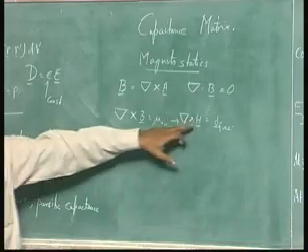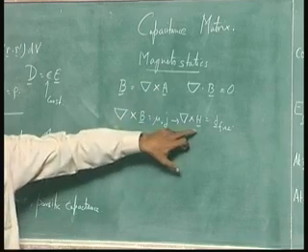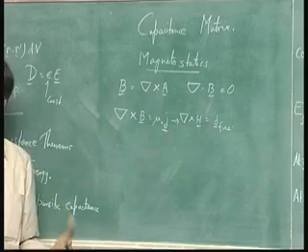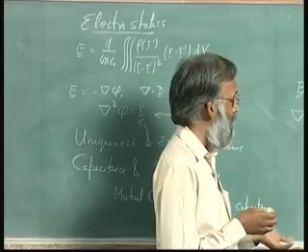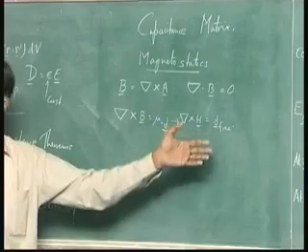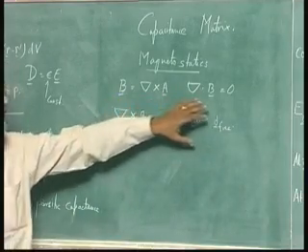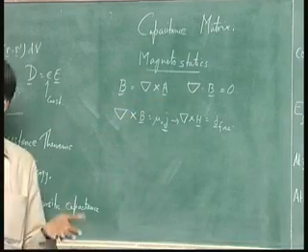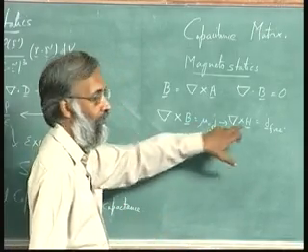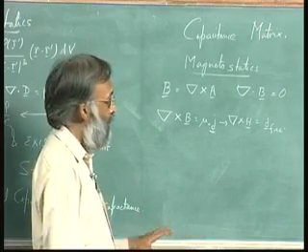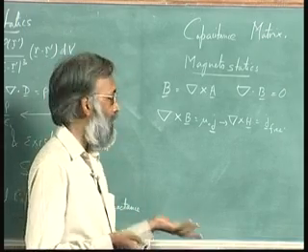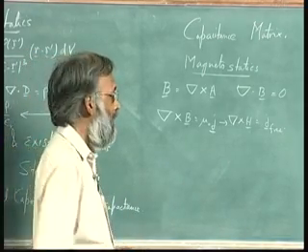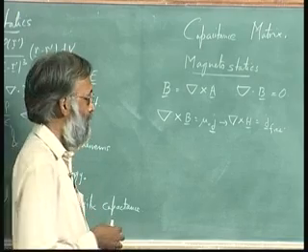The relationship between B and H is quite complex. So B is a nonlinear function of H. Not only that, it depends on the history of how H changed. So you have hysteresis, you have nonlinearity, you have everything inside these two equations. And most of the complications of magnetic systems come here, and I skipped all of that. So I am hoping that those complications will be covered better in courses which you will do in connection with machines and transformers.